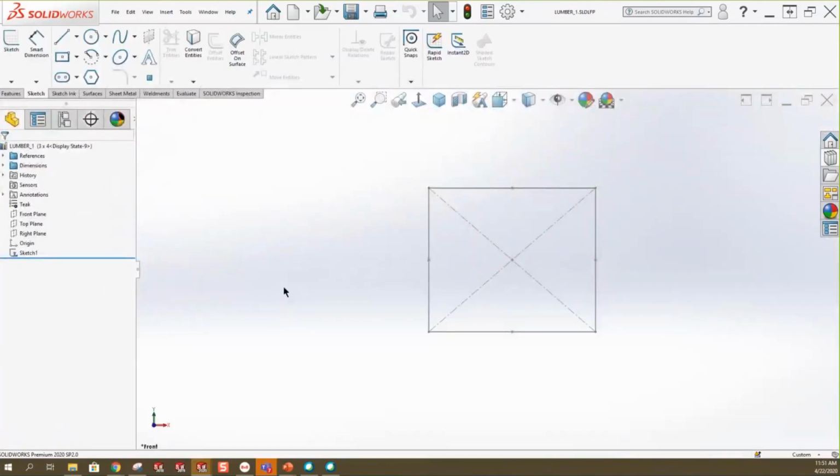And one of the cool things, and just letting you know, if you ever want to make your own weldment, feel free to open up an existing weldment. It is an SLD LFP, library feature part right here. Open one up, save it off of something else, and make it your own. All you have to do is go edit the sketch. It's already understanding that it's a library feature part, and it's going to work just like all the other profiles. So much easier than starting over, just letting you know.